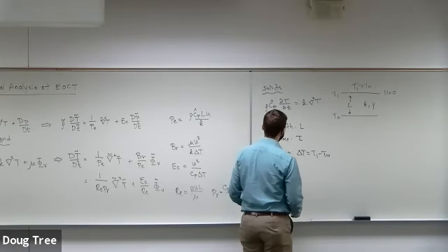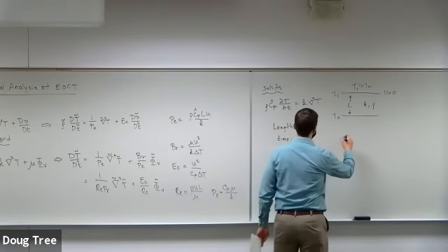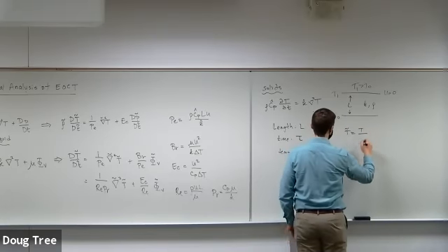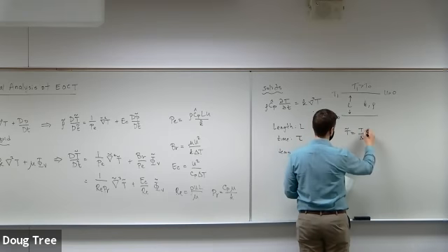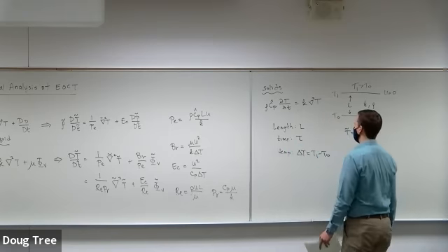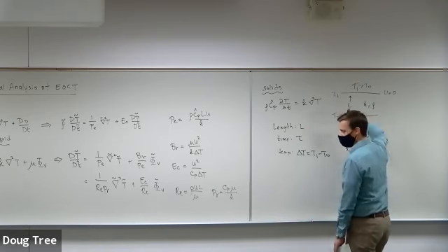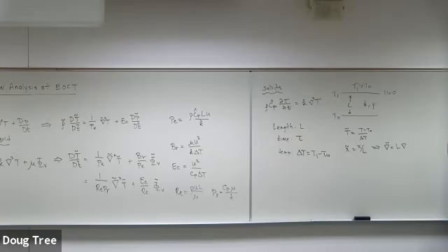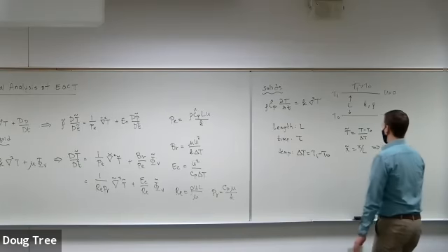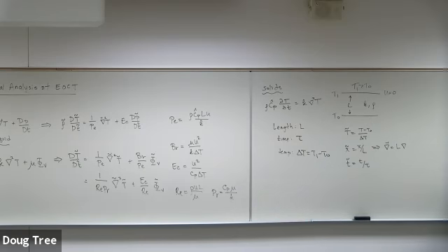Okay, so we can go ahead and define our variables in terms of these scales. We define the dimensionless temperature T tilde as T minus T naught divided by delta T. We want to define our x tilde as x over L. x is our dimension here, which in turn means that our gradients are given by L times the gradient, because the gradient has a d dx in the denominator, so L comes up in the numerator. And we might as well make our time t tilde be t divided by tau, this unknown time scale that we have yet to figure out.